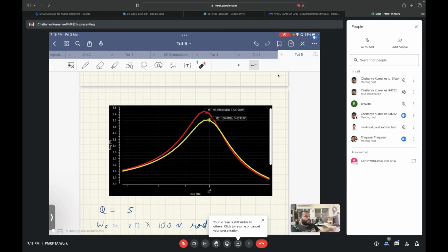Let's say you find the phase margin using calculations. You can actually build that circuit using VCCS. So you build the circuit using a transconductor and its output going to a parallel combination of resistor and capacitor, right? So you can actually build that circuit in LTSpice, do the simulation, do the AC analysis, and see the loop response for yourself. So those things you can do.